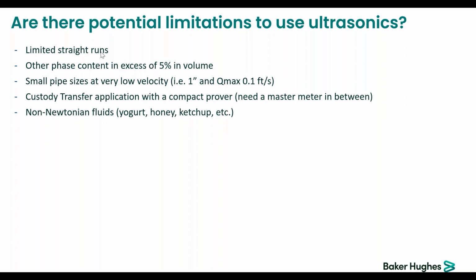If you have liquid in gas or gas in liquid, it needs to be minimized and kept below 5% in volume, not in mass, by the way. If you have a very small line size at a very low velocity, because we measure time, the difference in time will be very small compared to the electronics resolution, and it's probably not the best technology to use.